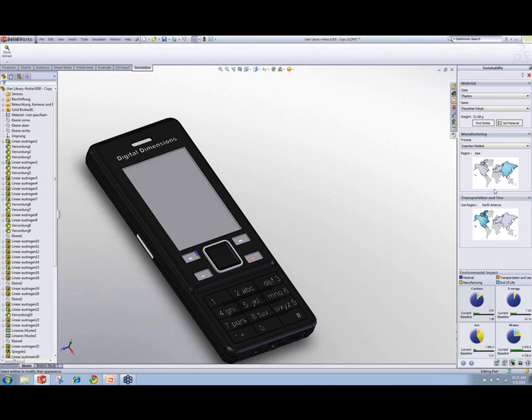All right. Once you've done that, you can see that the impact level has significantly dropped from aluminum to plastic. Now let's set a new baseline and see if we can find a better material than this polyether polyol. So I want to set a new baseline. I like where I'm going. So let's toggle on, off, and on the baseline.